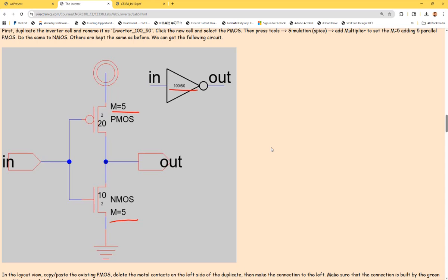So if you show an inverter symbol and show a number slash another number, it's actually the PMOS width versus the NMOS width. Like this guy. So that carries a lot of information. This is telling you which one's stronger, right? Because the wider transistor will be a stronger transistor. A stronger PMOS will be able to hold the voltage at the VDD for a longer time.